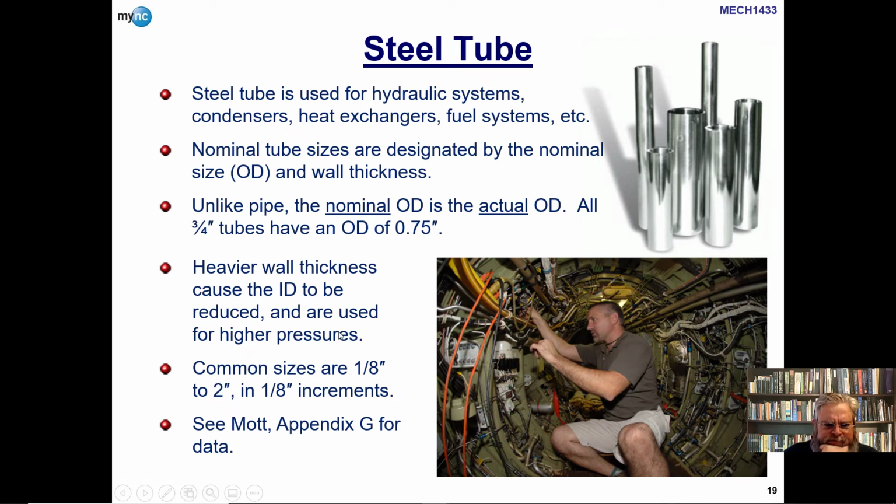The common sizes in inch series tubes go in 1/8 increments, but by actual standard sizes, it's 1/16. So anywhere from about 1/8 of an inch for quite a small tube up to about a 2 inch. Maybe they sometimes get bigger as a standard, but a 2 inch is getting to be a pretty big tube. And if you need tubes bigger than 2 inches, it's time to start thinking about pipes instead of tubes, it seems.